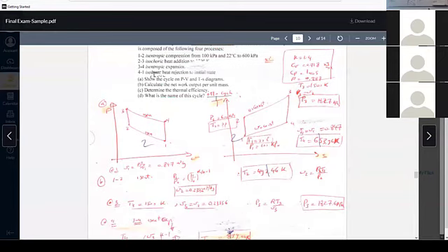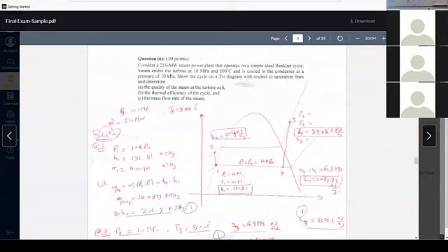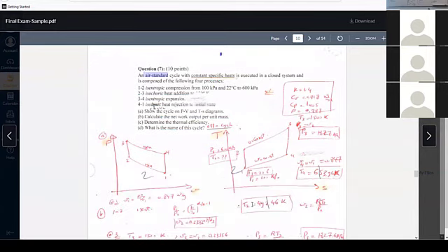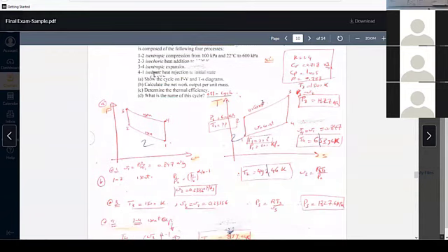So temperature, we need to make sure we have temperature everywhere. Here, you need H's, yes. You need H1, H2, H3, H4, yes. Rankine, you need H's. But for all air gases, all of them, including the special cycle, including Carnot cycle, we need temperatures. Temperature is always better. So always box this temperature, which is the best thing for you. T3 is given already.